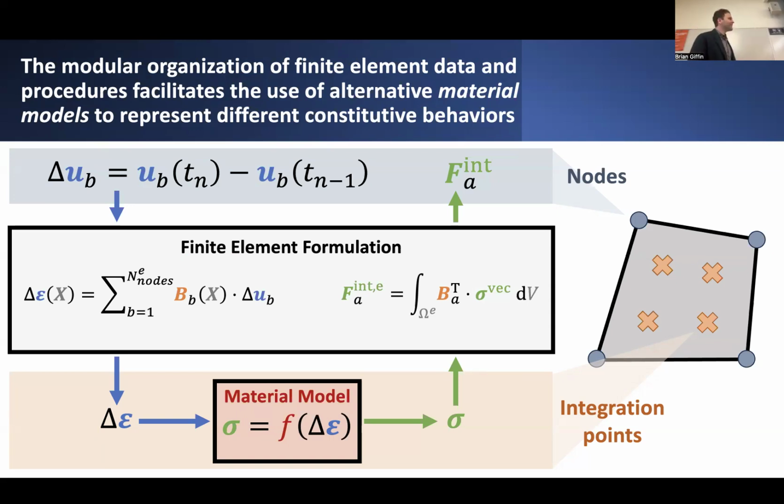The nice thing about this organization is that we've actually separated out this notion of what's happening in the material from some of the other steps we have to go through to actually formulate our finite element. So if you want, you can think of it kind of like this. At the nodes, we have things like the displacements, or more specifically, if we're doing loading in this incremental fashion, over a given load step, what we're looking at is the increment in the displacements of the nodes for the current load step.